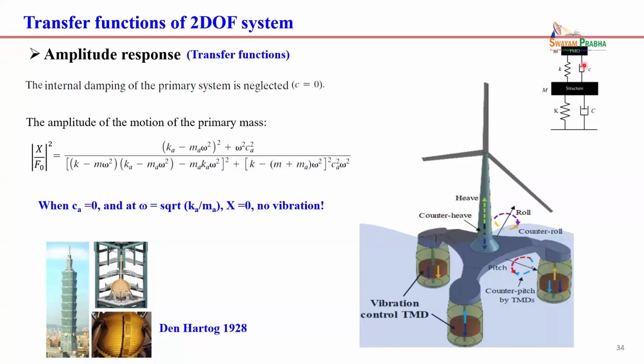And then instead of just using this damper, we can use the damper and the inerter connected together, right? Then that will have the effect of a tuned inertial damper beyond a tuned mass damper. What's the advantage? The advantage is we can reduce the mass needed. I told you, right? This one is 660 tons of mass. It's a huge mass, right?